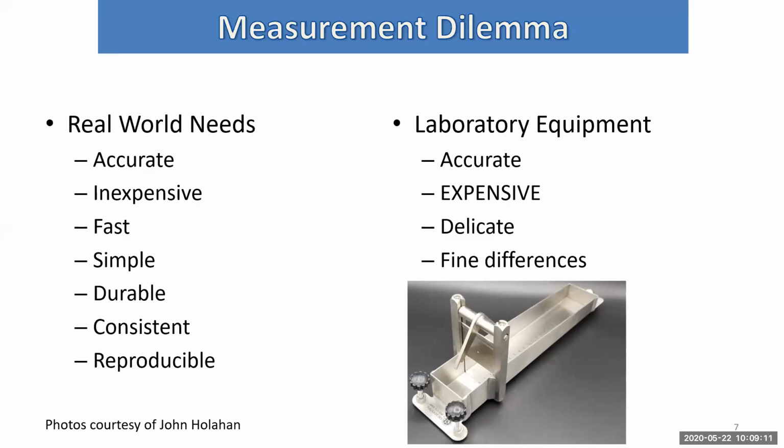There is no universal method for this device, but often 50 or 75 milliliter is the size of a sample tested, and you'll open the gate and test it for 30 seconds or maybe 1 minute. The Bostwick is a good test, except that it needs a large sample. It takes a relatively long time to run, and the device costs about $500 US.